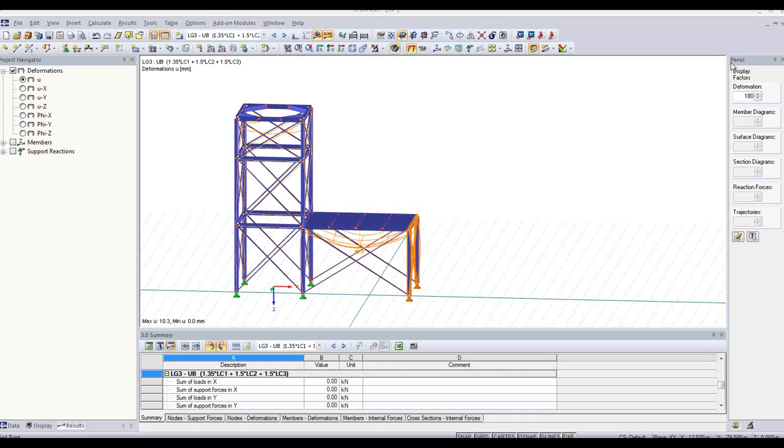One thing I'd like to point out is that Chelsea created load groups. Load groups are actually what you might know better as load combinations from code or other programs. And there was another so-called load combination that we create in our software, and this includes the maximum and minimum forces or results of the analyzed load groups. So we also have things like an envelope load combination in our software. It's called load combination.